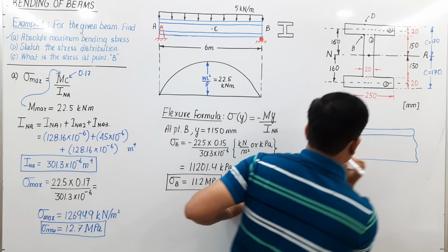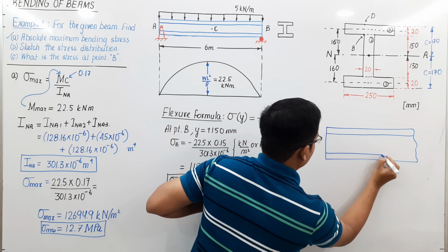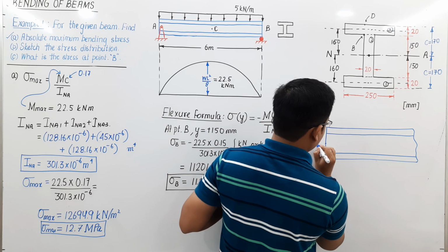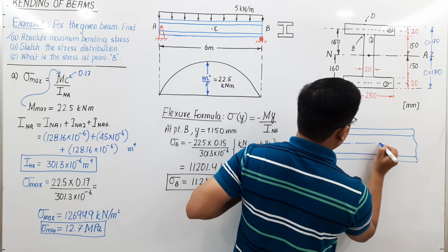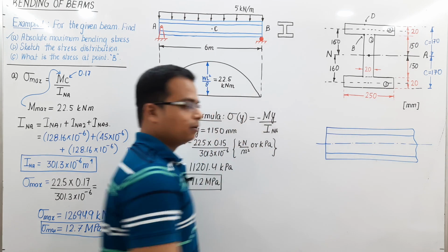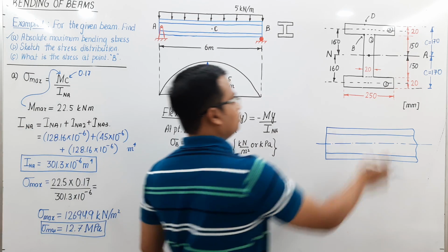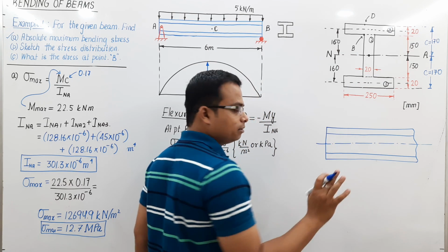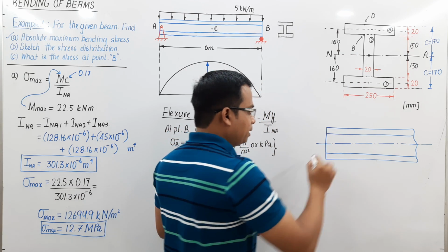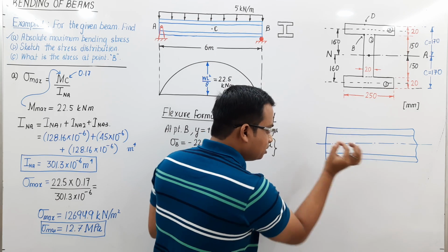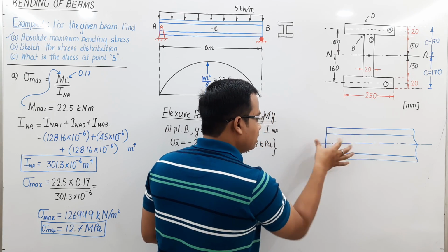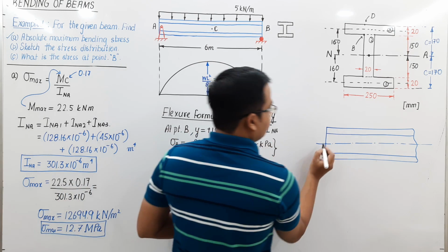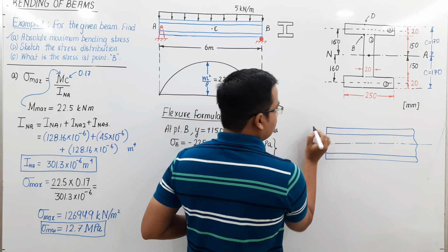Top portion, something like this, bottom portion, and that's the longitudinal axis, which in fact becomes your neutral axis in the side view. Okay, this at a height of 170, this is also at a height of 170. That's quite true. Anyway, the bending moment is with respect to an axis perpendicular to the plane of the board, and that is your neutral axis, which you cannot see in this view. Anyway, we are interested in making the profile.